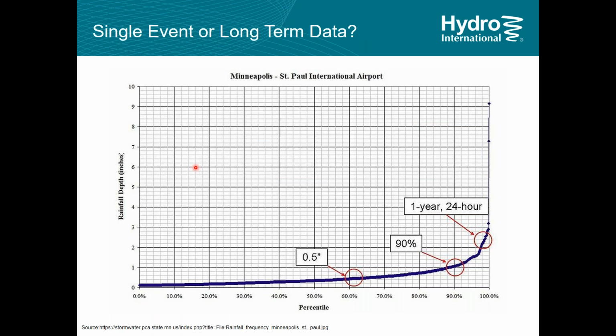And when you look at this on a long-term rainfall record, when we look at sizing on a net annual basis, it's heavily influenced by these small storms, so you end up with a piece of equipment that's sized, say, to treat this area here. When I size on a peak or event basis, I might size on a 1-inch rainfall. I end up with a piece of equipment that's set to treat this rainfall to 80%.